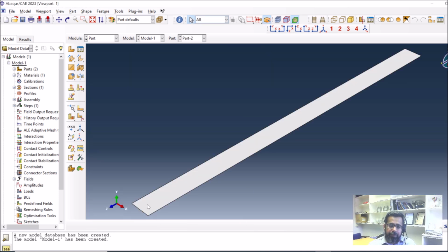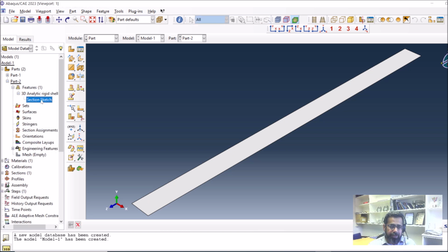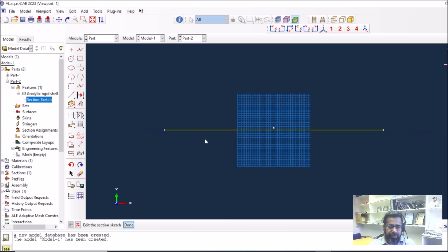Now if I put the pipeline here along this length in the assembly module, then we don't have any space for that fish trawl to drag. So I think it's better to increase the width of this to a much higher value. So I'm gonna go back, and I'm gonna change the sketch here, and I will change these dimensions. I can change the dimension, or I can increase the length. So maybe I will just go with some